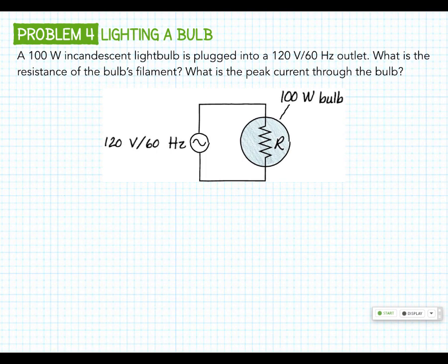So it's set up so that you get the average power, because power is the thing that we care the most about, all right? So our resistance is just going to be V_RMS squared over power, just because power is V squared over R, okay?